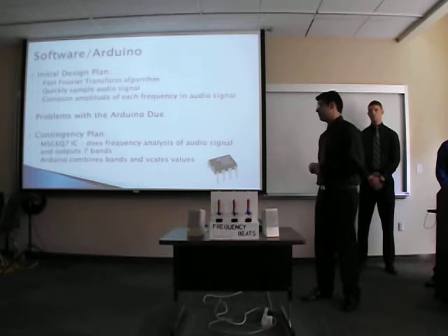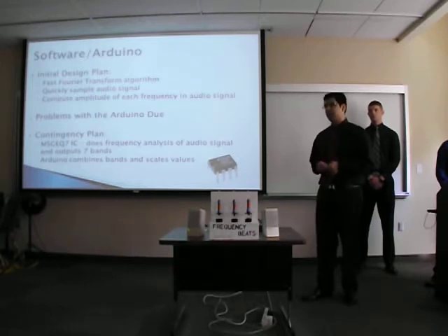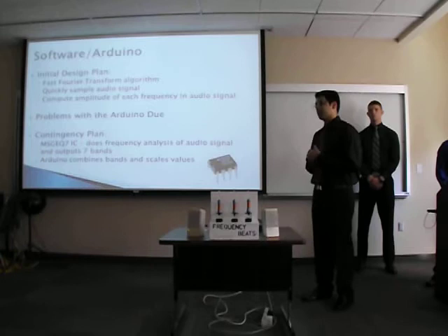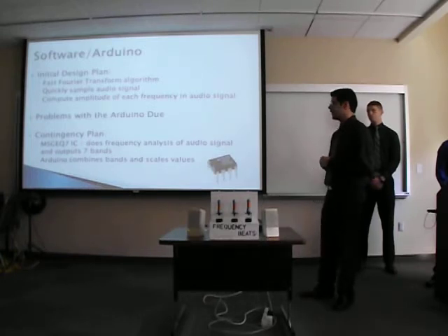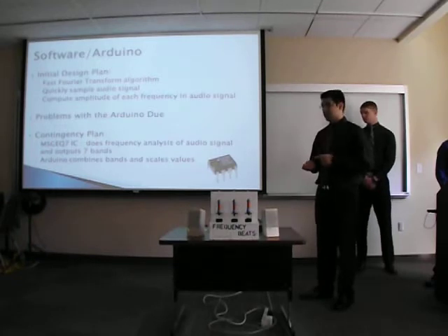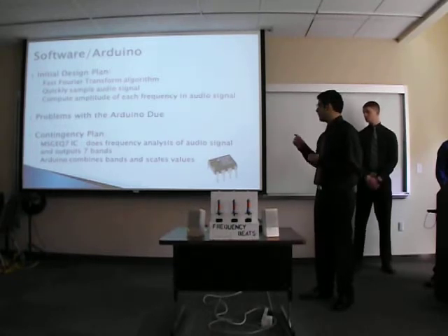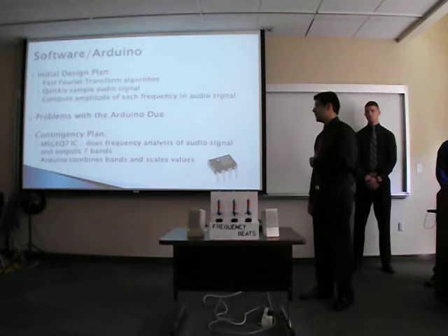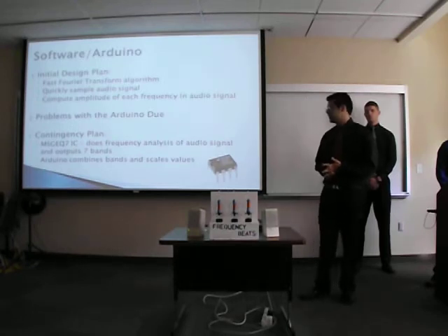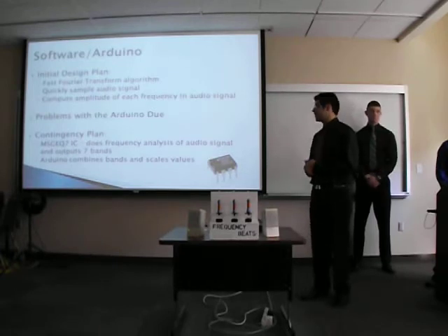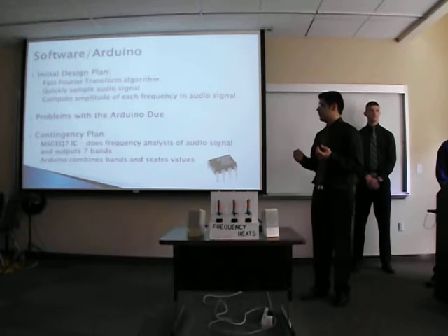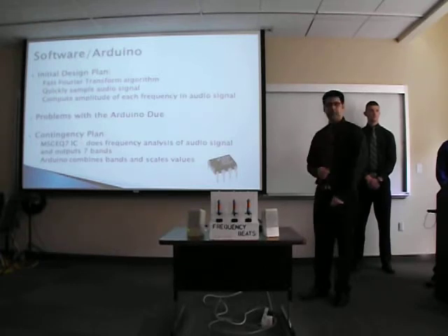So at about a month into the build stage, we had to come up with some plan that would allow Alex and Kevin to actually troubleshoot their magnets. So instead of using the Arduino to process, we swapped it out for an 8-pin chip, the MSGEQ7, which basically does the processing for us. It wasn't very clean or exact, but it gave us the 7 bands that we needed to produce frequency outputs needed for their testing.